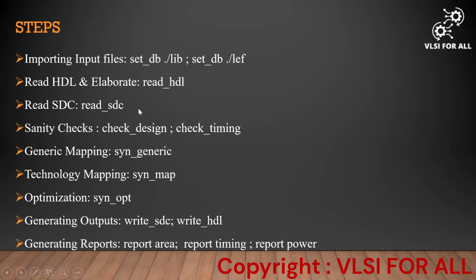In this step, as usual in logic synthesis, the timing constraints and design constraints given in the SDC file will all be read and applied to the design. The next step is sanity checks. For this, again the commands are the same, like check_design, check_timing. The next step is generic mapping. In generic mapping, the command is syn_generic. The mapping will be done here. The next step is technology mapping. For this, the command is syn_map. After technology mapping, again comes the optimization. For the optimization, the command is syn_opt.